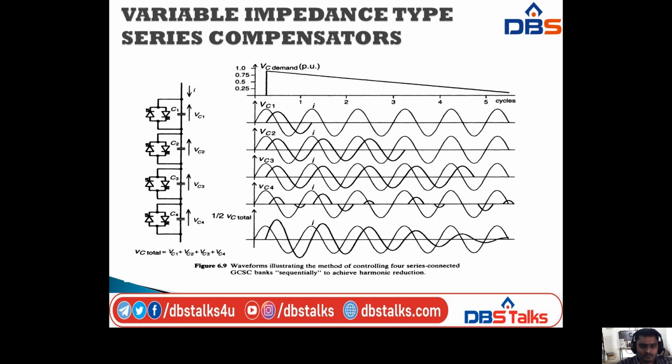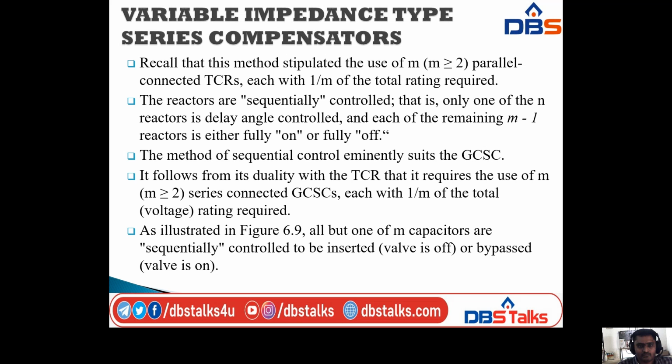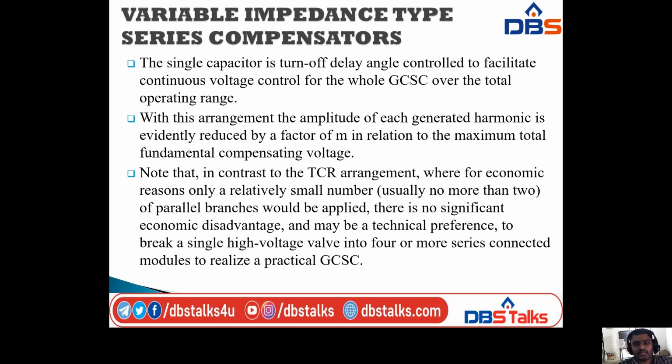Next, the single capacitor is turn-off delay angle controlled to facilitate continuous voltage control for the whole GCSC over the total operating range. With this arrangement, the amplitude of each generated harmonic is evidently reduced by a factor of m in relation to the maximum total fundamental compensating voltage.